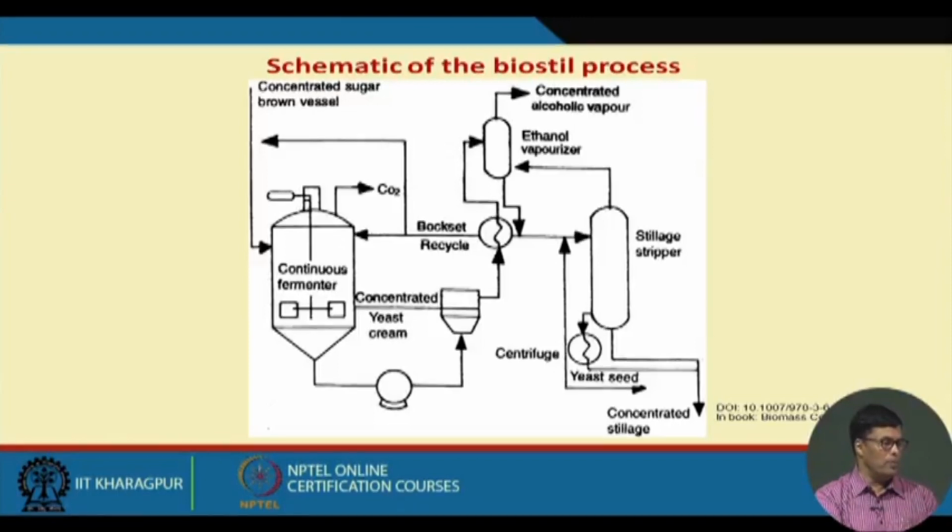So we have to dilute this cane molasses significantly. A significant amount of water is required. Now if you can recycle this effluent, then the effluent contains some unconverted sugar that will get an opportunity to ferment further, and also water consumption in the fermentation broth will be reduced to a great extent.